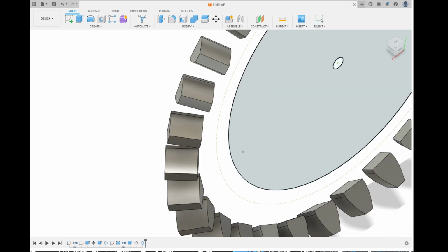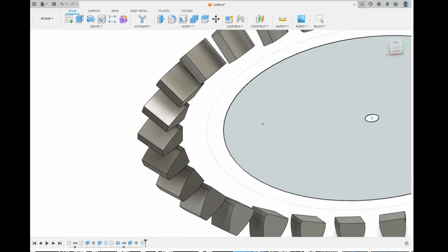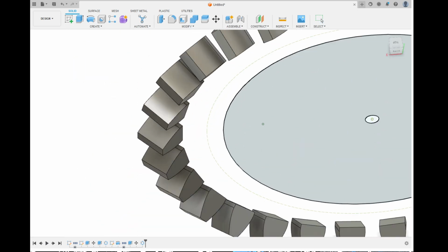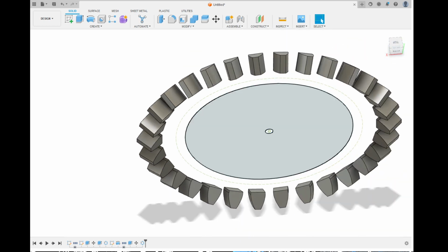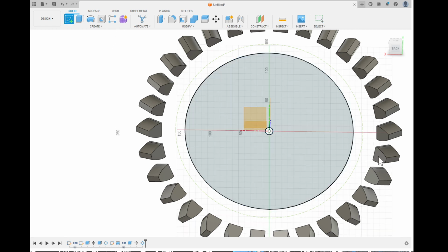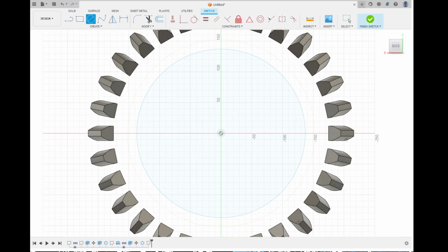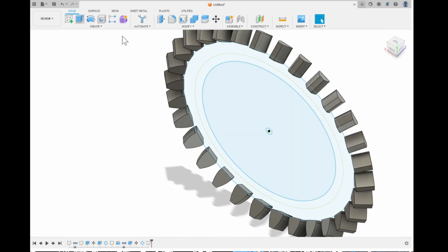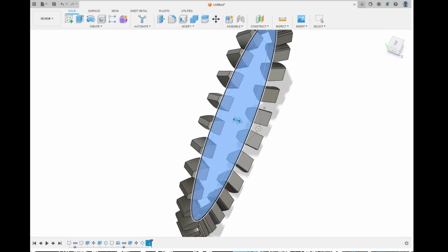Okay. And then like our previous one, we have to make a shape that can fit around it. Now I think, is there another way I can make the shape that would make sense? Probably. Sketch this face over here. Can I just make a circle? I'll go here. Do that. Finish sketch. And then I can get this circle. I can extrude this circle out.